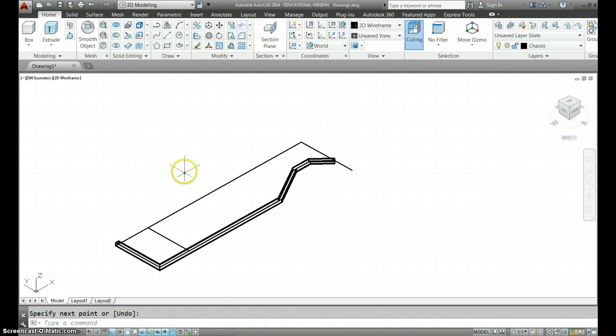So I'm going to put in the other nodes, but first I'll draw the box, and I'll rotate the box and put it onto the end of the node. But this time I'm also going to copy the box along. So here we go. Let's go to line, pick on the screen, move the mouse in this direction, 25, enter, that direction 25, enter, that direction 25, enter, set to close, enter.